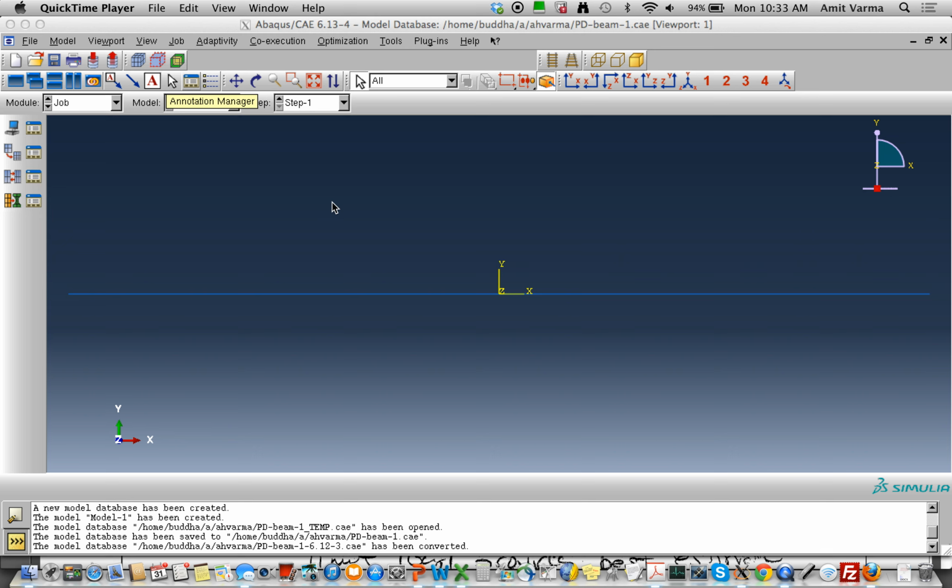That's curve number two. And we looked at solving this problem, which is a fixed beam. It's fixed at both ends, and it is subjected to a concentrated force acting at a distance of 3/4 m. And the properties of that cross-section were given. We had the moment of inertia I, we had the plastic moment 1500. But when I go to build my finite element model, as you can imagine later, I'm going to need a little more. So it's a W14 by 26. So I looked it up. It's a W14 by 26 cross-section that we're looking at over there.